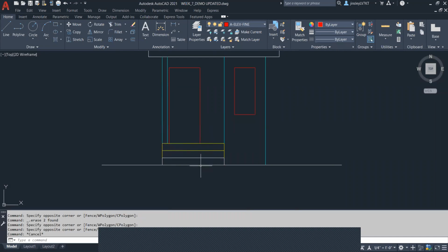So the way that we would do this, if you remember with polylines, okay, here's my polyline. If we go to P-edit, we can set a width of 2, and we can give this a heavier line. This is kind of what we would do working by hand. We would take a soft lead and we would scrub that line so that the ground line looks a little bit more defined. It gives the elevation a little bit of weight, makes it look sturdy.